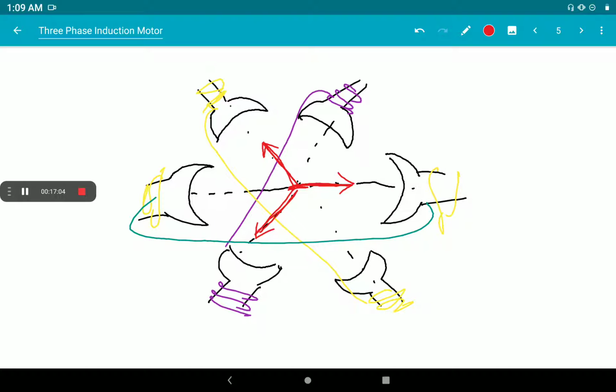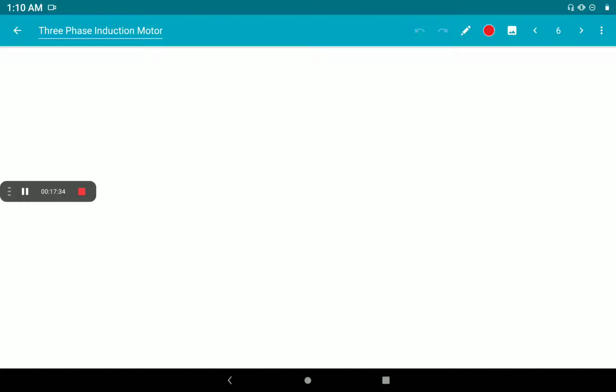Okay, so we use 3-phase supply having some amplitude and 120-degree phase shift. We place the stator conductors physically located in space 120-degree apart, and the current from the source is going through this coil. Okay, and a combination of these two constraints produces a rotating magnetic field. So we should remember how to produce a rotating magnetic field.